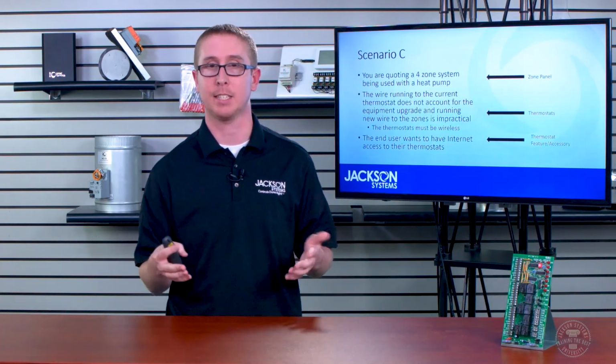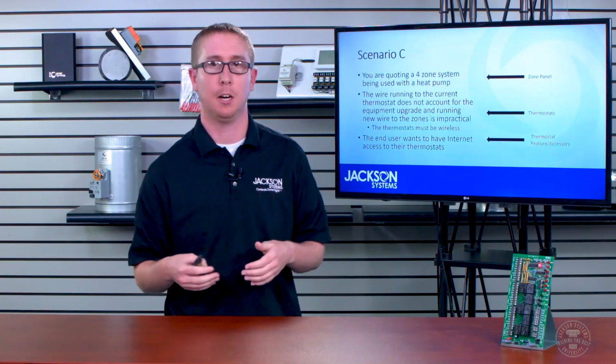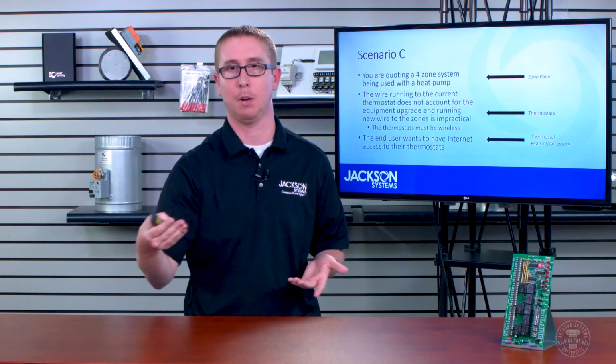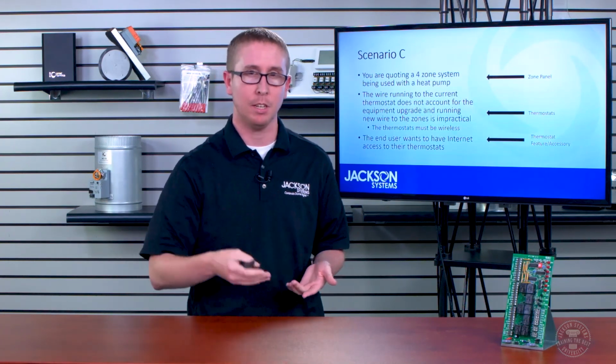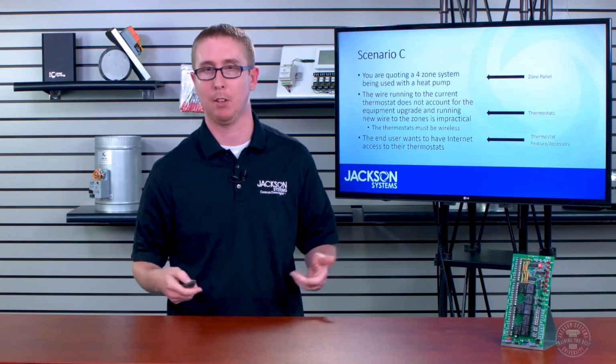And last but not least, the end user, whether it's a homeowner or a small commercial building, wants internet access on these thermostats. So the internet access and the thermostats being required as wireless is going to dictate what thermostats we're looking at. And the 4-zone system with heat pump compatibility is going to dictate the zone panel that we're looking at.